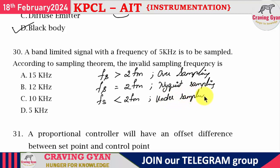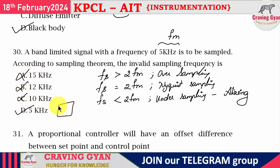Undersampling. So here you will be getting the effect that is referred to as what? Aliasing effect. Aliasing effect. So the highest frequency component is 5 kilohertz. Greater than or equal to 10 kilohertz is what you should get. Then that one is the valid sampling frequency. So option D, that is 5 kilohertz, is the invalid sampling frequency.